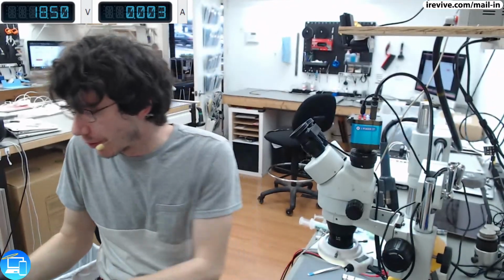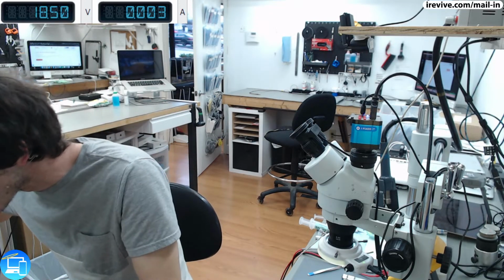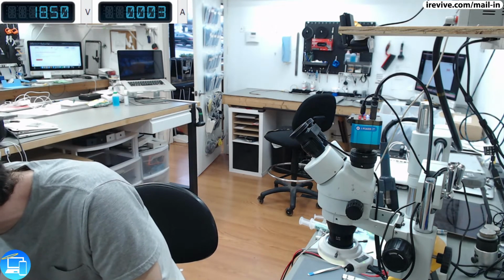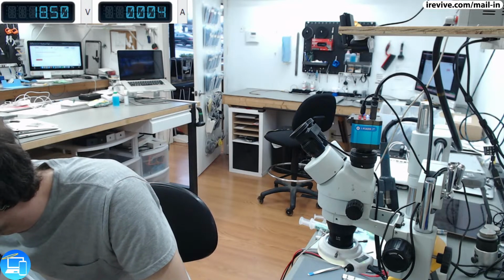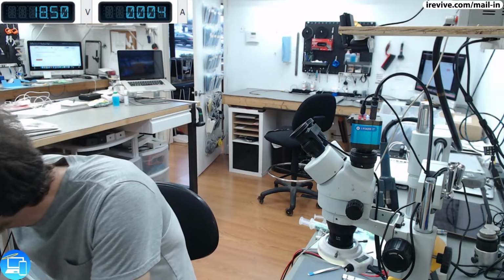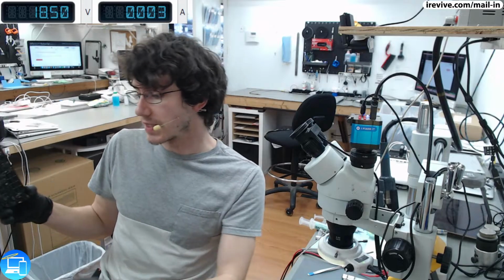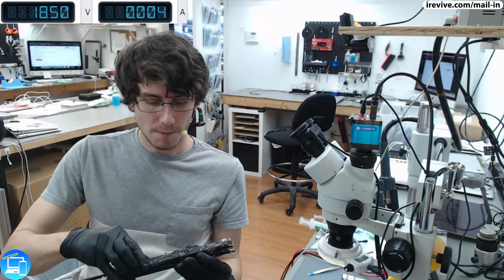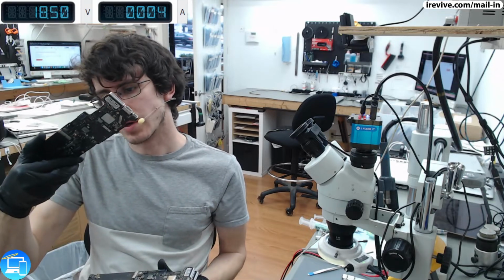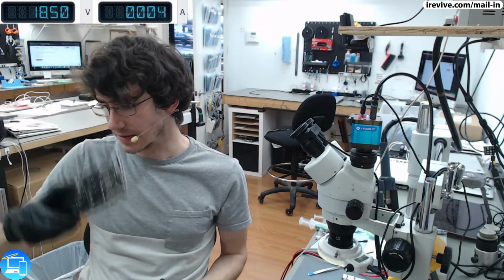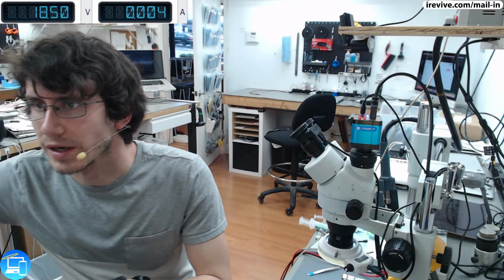Alright, so we need a donor board. The nice thing about the 820-00165 is it actually uses the same components as, I want to say, the 3437. Let me see, I got it right here. A 3437, which is going to be the 2013-2014 MacBook Air. But I have plenty of 820-00165, so I'm just going to pull straight from this board, since we know that it's the exact same model. These are the data lines, no power lines, so you can use thin wire.